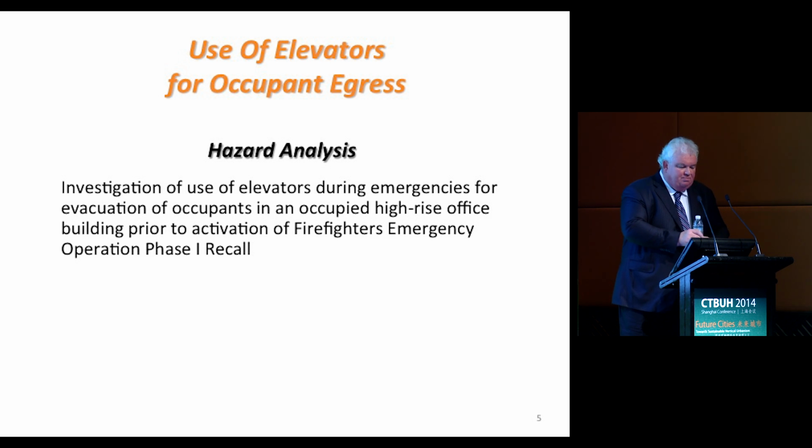Now, the hazard analysis process that we followed specifically was an investigation of the use of elevators during emergencies for evacuation of occupants in an occupied high-rise office building prior to the activation of firefighters' emergency operation Phase 1 recall. I hope everyone's familiar with what we call Phase 1. That's when all of the elevators are recalled from the upper parts of the building down to the main floor whenever a fire alarm initiating device is activated.